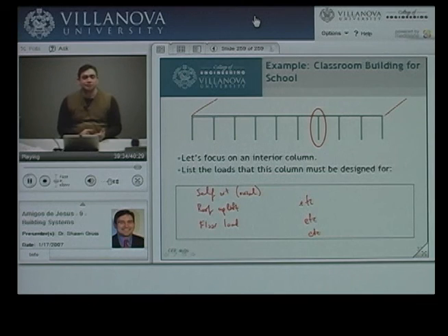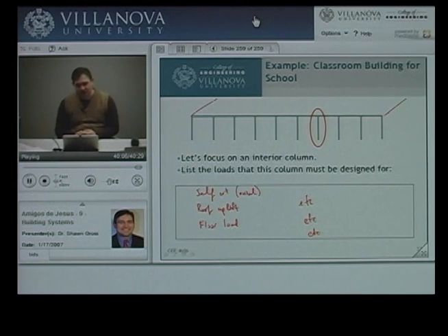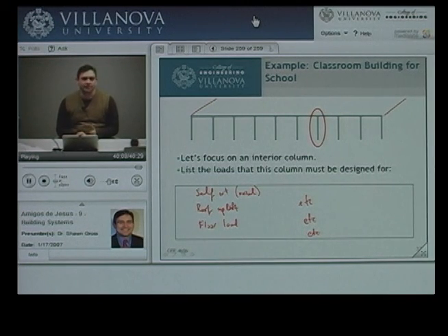So to recap, you need to choose your structural system. You have two options. You either have the bearing wall system or the building frame system. You're going to need to find some shear wall locations that make sense. Granted, you don't have the shear wall designs. You don't know exactly how big they need to be. That's fine. Make some guesstimates. Ask some questions and we can guide you through that process, but look at least for the obvious locations to put shear walls, and then start looking at which individual elements are going to have to handle which different types of load, so that we can proceed, once you have the magnitudes of those loads, to design those elements.